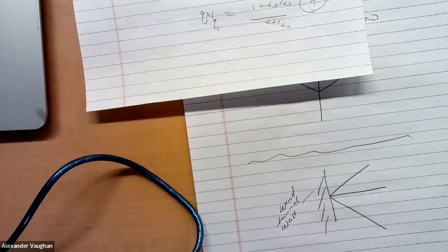And there's a group at Caltech, Professor Garib and his students. He's had several PhD students who looked at the swept forward case, the flag. And what happens is it diverges. But then if you go past the divergence speed enough, there's a nonlinearity in the structure that prevents it from going off to infinity, right?